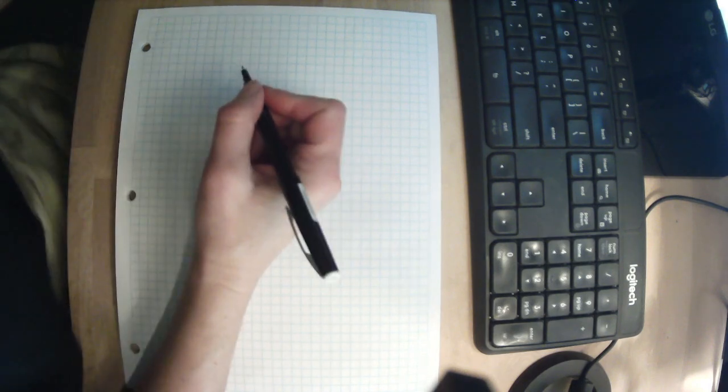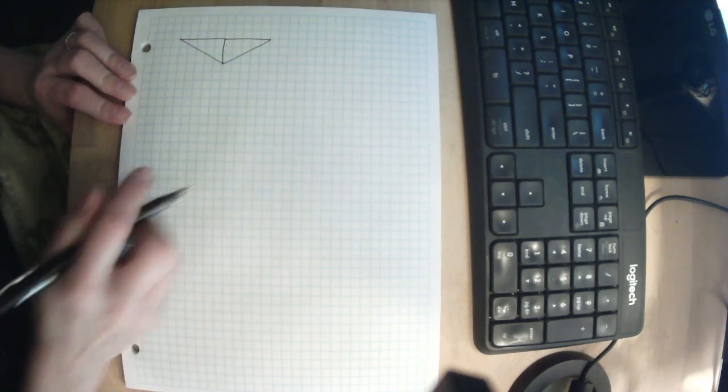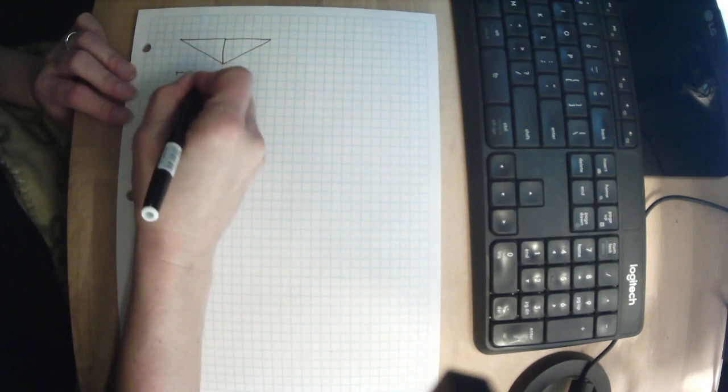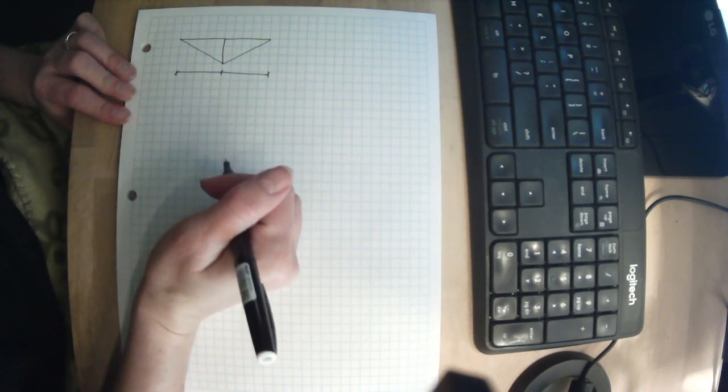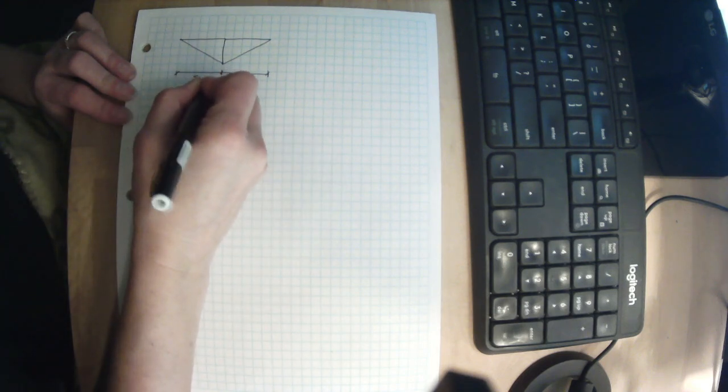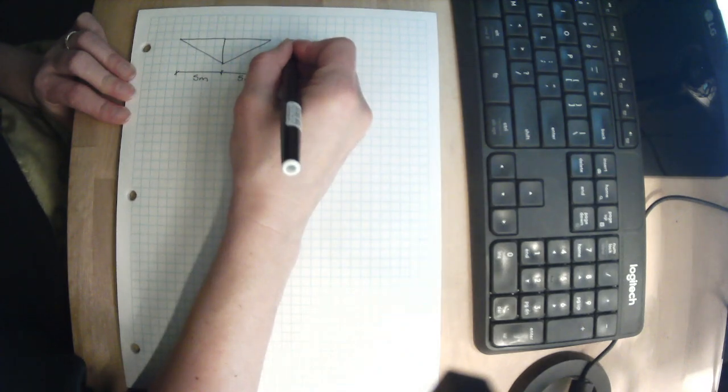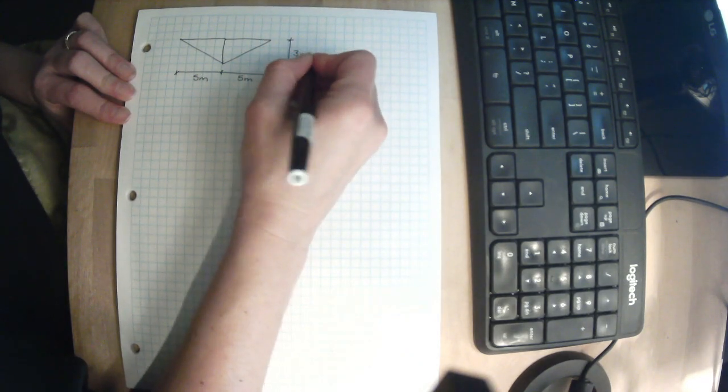So let me make this bigger. All right, so let's start solving this. I always find it handy to redraw my object. Something about drawing it helps get your head around it. So this is our object. We can put some dimensions on this. A free body diagram always has all the applied loads and reactions and all the dimensions. So this was 5 meters. And they told us that this was 3 meters.